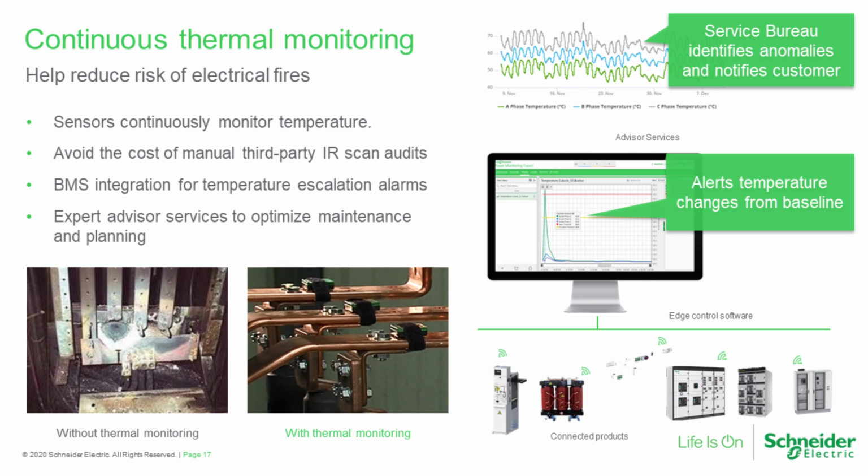There are actually measurements inside these critical pieces of equipment where if we measure at bus bars in certain critical locations, we can make a pretty good guess as to the health of that equipment. So these technologies involve sensors inside these pieces of equipment. You can alert based on temperature changes from a baseline.